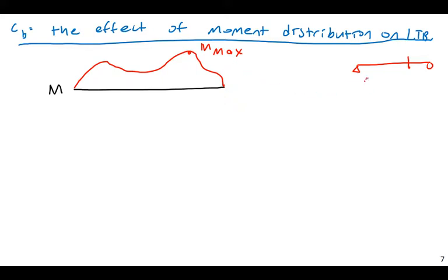If you think of your beam's cross-section like this, the only way it's going to just buckle out, like we've talked about previously, in lateral torsional buckling is if there is moment all the way along it. That's the only way that's going to work. So for example, if I just applied a couple to a beam, in other words, if I could somehow apply a pair of couples so that most of the beam was not under bending, only the middle section was or something like that, in that particular case, I wouldn't actually have buckling. So for example, I could do something like this.